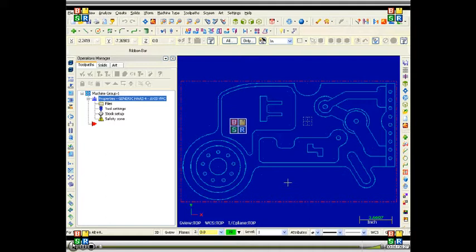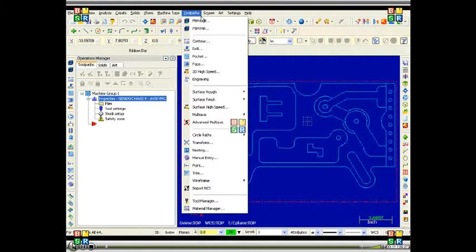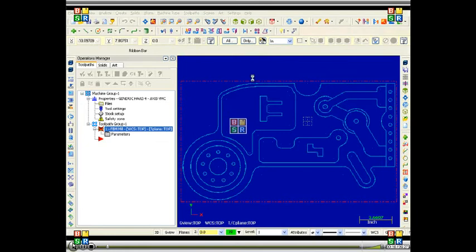In this video I'll run FBM mill for all the milling operations. After that I'll verify the toolpaths, comparing the results to part geometry. So let's get busy. Up into toolpaths and I'm going to select FBM mill.